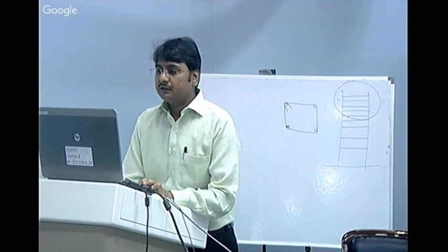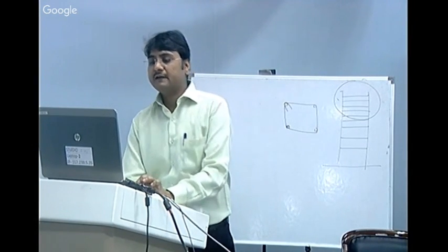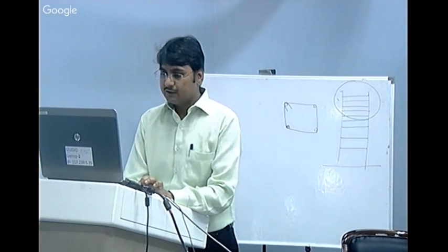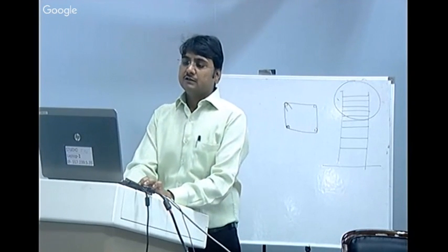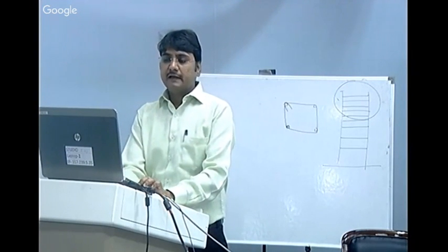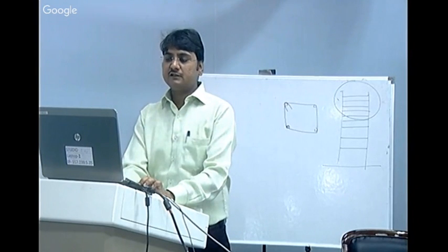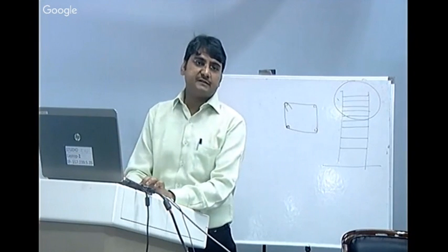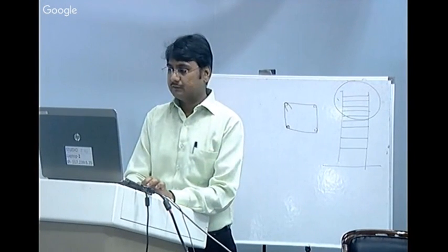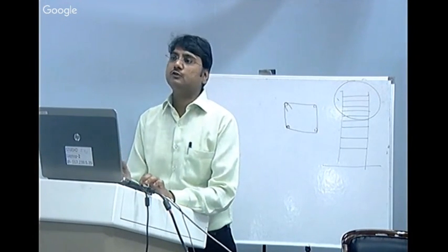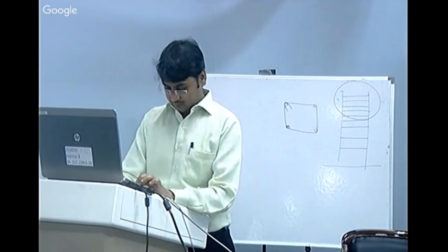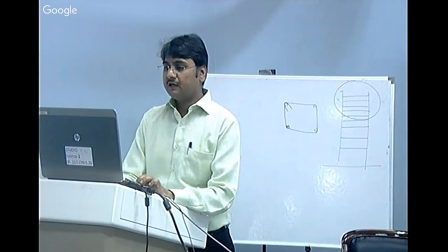Now here it is written table number 6, recommended longitudinal steel reinforcement. Here you know all the things are given, steel bands and how you need to provide the steel reinforcement in the column and beam for horizontal and vertical bands. Don't worry, I'll do it with you also. So from here you need to design your building.